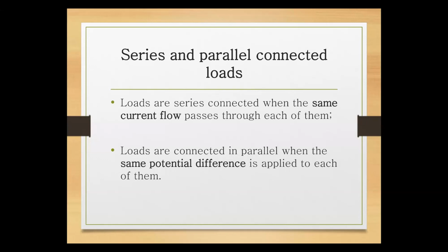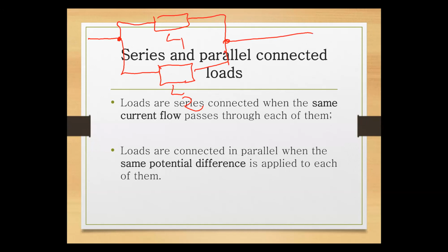You see, series is in, out, onto the next. But parallel, they are sharing. For example, this is a node or junction. Now we have L1, load 1, and then load 2, and then we go on and meet again. So you see that instead of going in and out of one load and then into the other, they share. Here it's split into two, goes into L1, goes into L2, then they meet again on the front. This is what is called a parallel connection.